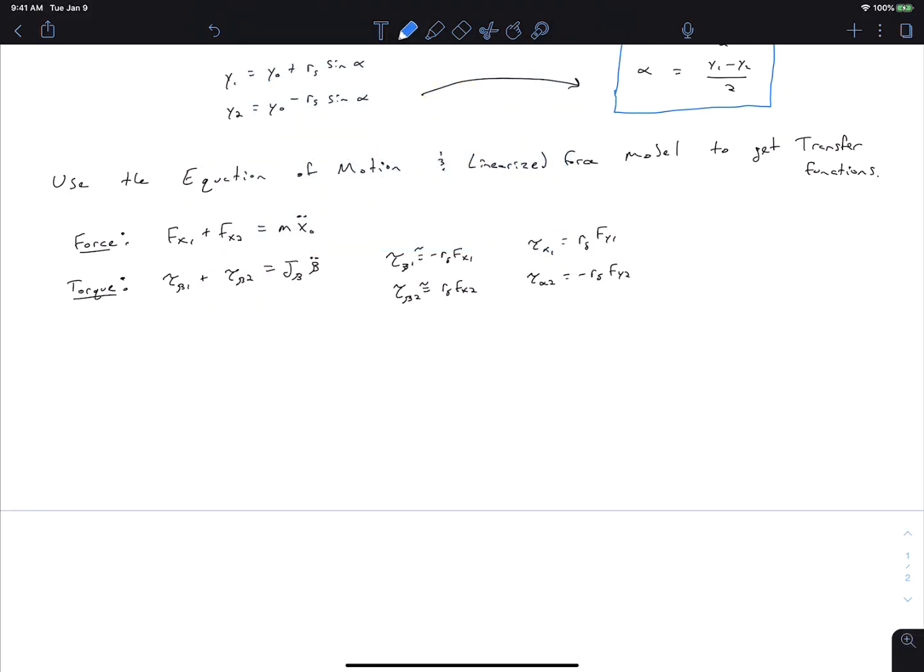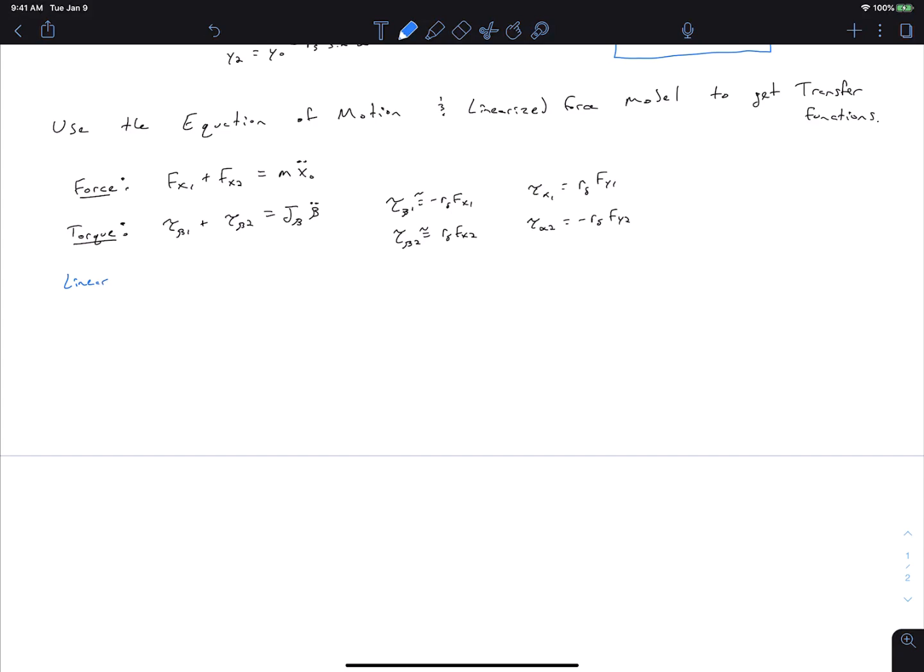And the linearized force model, as you'll recall, is this equation that the force is equal to a kf times a current plus k delta times our delta displacement. And for this model, we're going to modify it slightly. We're going to say that we have k delta by 2 times our displacement. And we're doing that to reflect that we have a total k delta, which is when we have both magnetic bearings acting at the same time. So we split k delta between the two magnetic bearing units.